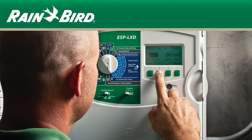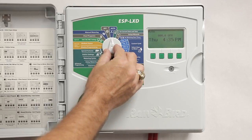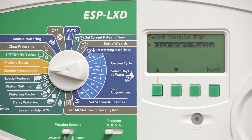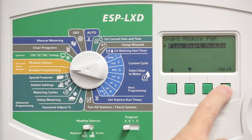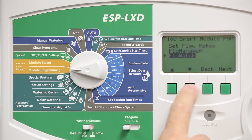This video covers programming the FlowSmart module using the ESP-LXD controller, including FlowWatch and CEIF/SELF. Continue by turning the dial to FlowSmart modules, Module Programming. Select FlowSmart module, which is the only choice at this point. Press Next, and select FlowWatch from the list.